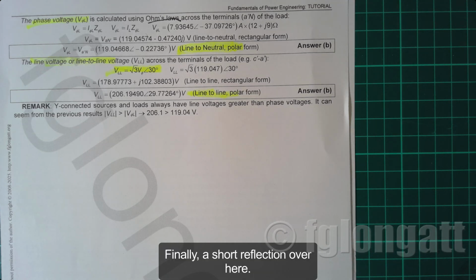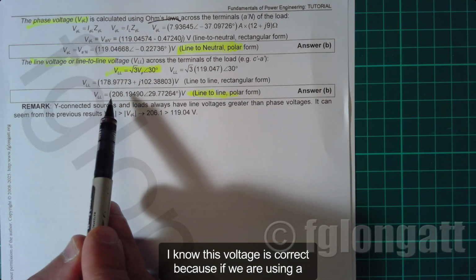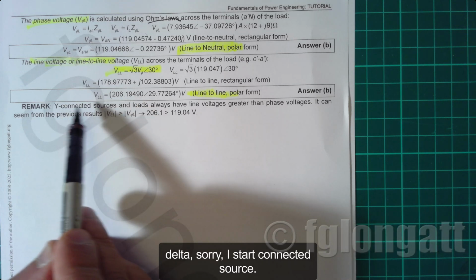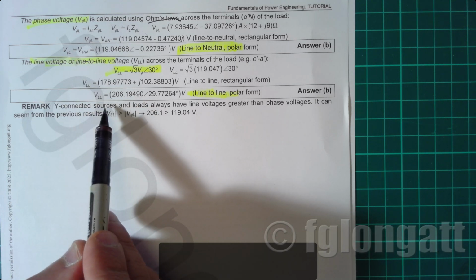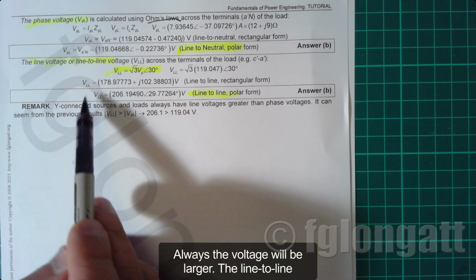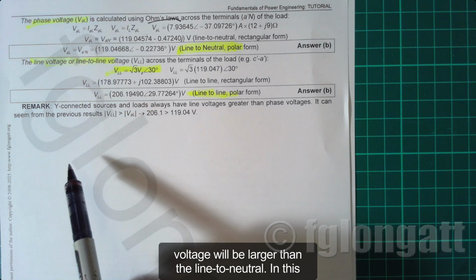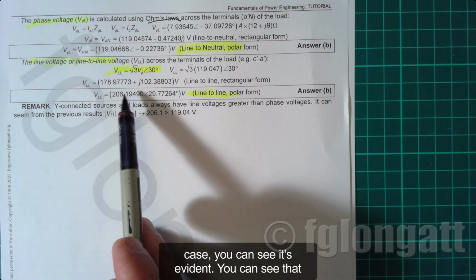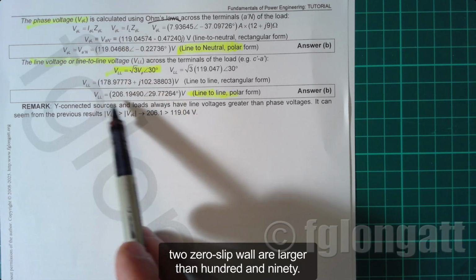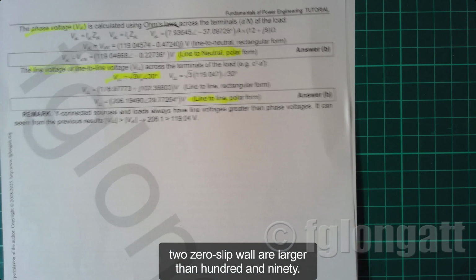Finally, a short reflection over here. I know this voltage is correct because if we are using a star connected source, always the line-to-line voltage will be larger than the line-to-neutral. And in this case, you can see it's evident. You can see that 206 volts is larger than 119.